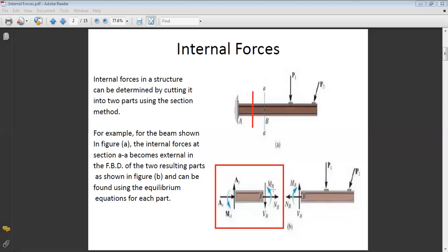Okay, here, when we put MB in this way, it will be negative, because when we do calculation, MB should be in the opposite direction, and the same for M. We will see together that we have a certain convention for shear, normal force, and bending moment. I will introduce them after.